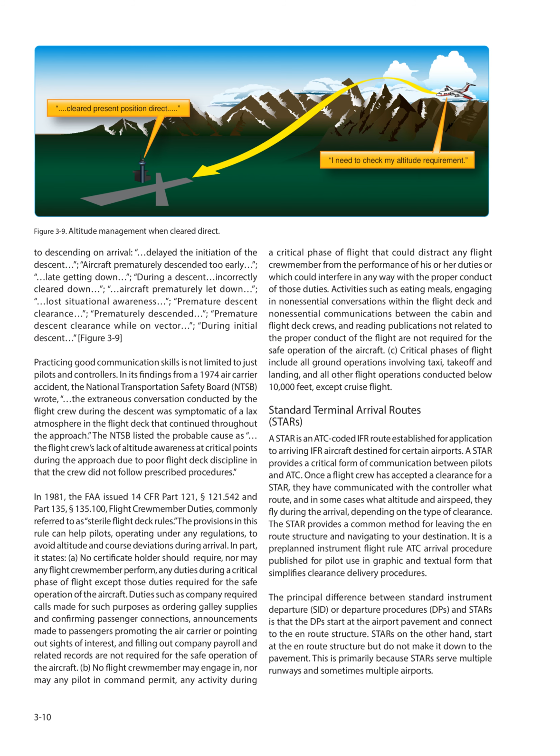In part, it states, "No certificate holder shall require, nor may any flight crew member perform, any duties during a critical phase of flight except those duties required for the safe operation of the aircraft." Duties such as company-required calls made for such purposes as ordering galley supplies and confirming passenger connections, announcements made to passengers promoting the air carrier or pointing out sites of interest, and filling out company payroll and related records are not required for the safe operation of the aircraft. No flight crew member may engage in, nor may any pilot in command permit, any activity during a critical phase of flight that could distract any flight crew member from the performance of his or her duties or which could interfere in any way with the proper conduct of those duties.